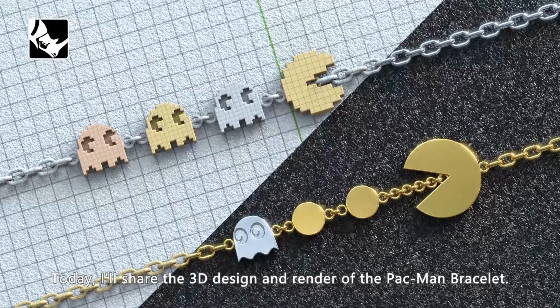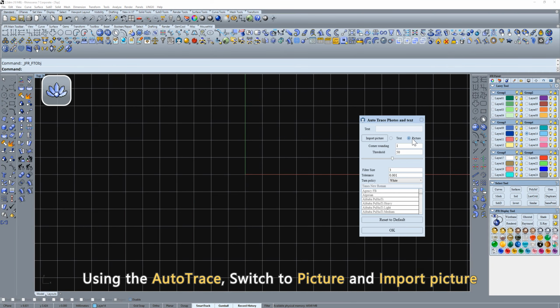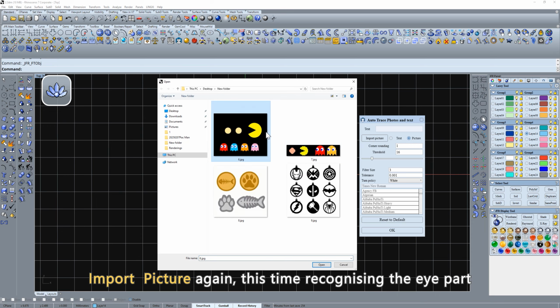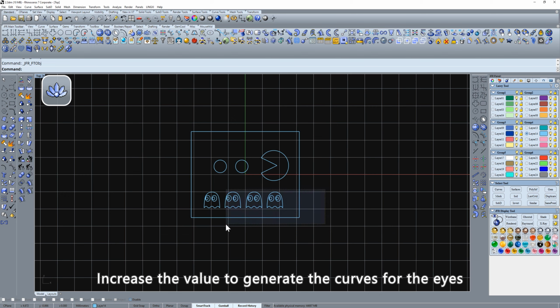Today, I'll share the 3D design and render of the Pac-Man bracelet using the auto trace. Switch to picture and import picture. Modifying the threshold will identify curves based on different colors. Import the picture again, this time recognizing the eye part. Increase the value to generate the curves for the eyes.